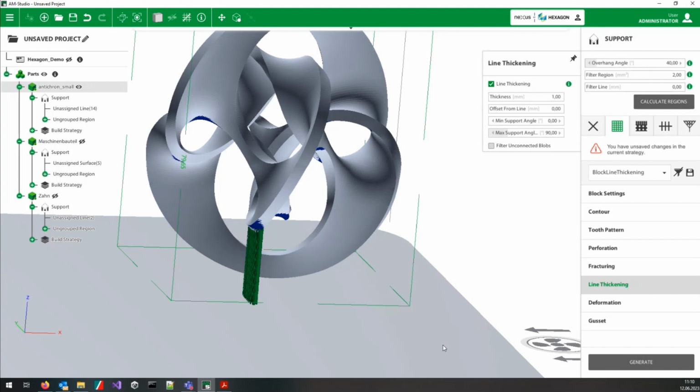Okay, so if I cannot select the surface, is there any option to avoid internal support where I will not have access to remove those supports? If you're using external support, you don't have the options to manipulate it, because then it's interpreted like a mesh, like an STL. So you can only manipulate, update or edit existing supports if you're using AM Studio ones, for sure.